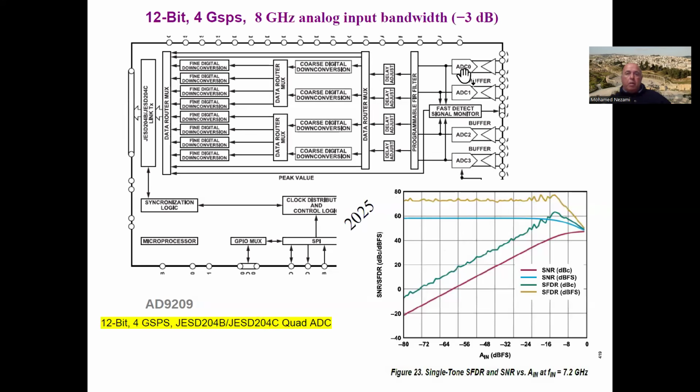As you can see, the ADCs in here, this is the input. And the first thing you see is there's a finite impulse response filter right at the output of the ADCs, so you can filter your samples, and then you can adjust the delays between these. The purpose of this is for systems like phased array systems where you're trying to coherently obtain a reference that is fixed, with no timing error between them.